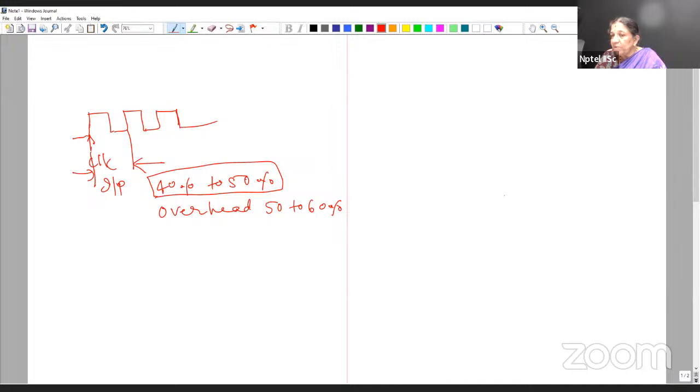So we worked out some of the problems in that also, how we can reduce the voltage levels. If it is 5 volts, then by selecting a proper beta based on your pipelining and parallelism, we can reduce it to beta squared. That will be the operating voltage of your circuits. So that we have considered. Later on, we started using filters. Basically, we did FIR filters and then IIR filters.